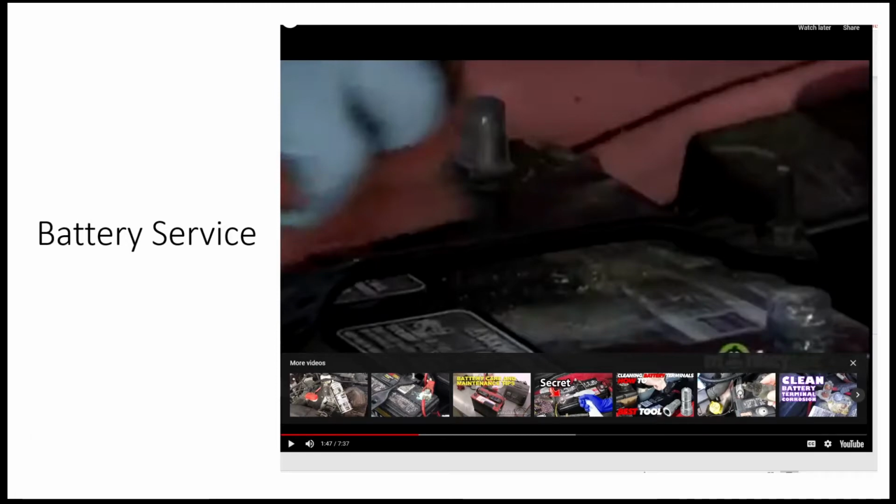I want to put a note in here. Do not take a rag and clean off the excess, guys. Unacceptable. Don't do it. One, you're contaminating the rag, filling it full of battery acids and junk that shouldn't be in a rag. That's a safety hazard for the shop. What if somebody picked that up and wiped their eyes, in a worst case scenario? Super dangerous. Don't do that.